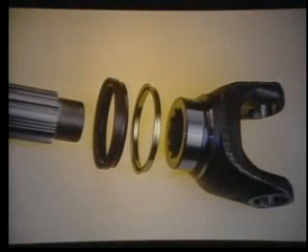Remember, any seal will leak if the mating yoke seal surface is worn. And if you are replacing a seal because it is worn, it is unlikely the yoke will be usable in its current state. If the yoke is worn, the only acceptable repair other than installing a Fuller sleeve kit is to replace the yoke. Most transmission models can then be updated by installing a NOK slinger seal and new yoke with a hardened seal surface.